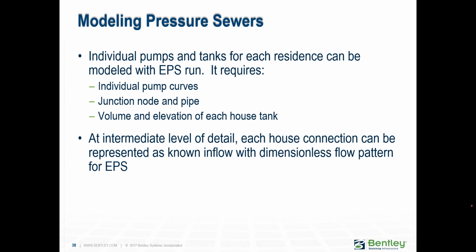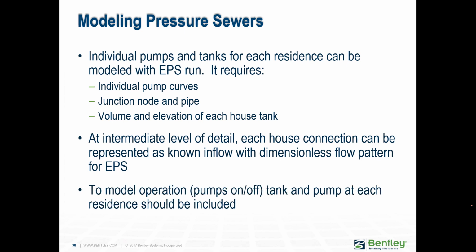So you could do an intermediate level of detail where you would represent a house connection as a known inflow, as in an extended period simulation. So rather than entering the pump curve and the pump controls and all that, you simply say, okay, at this house, this is what the inflow would look like. And you just enter a flow versus time inflow.